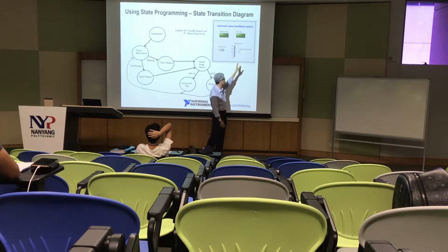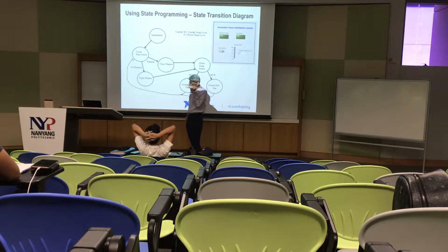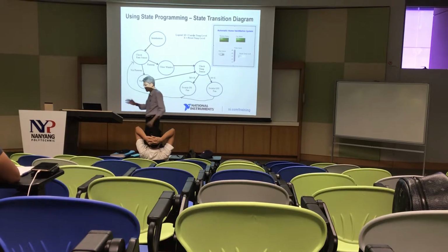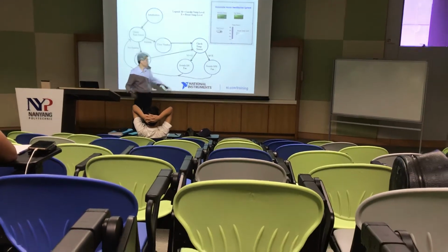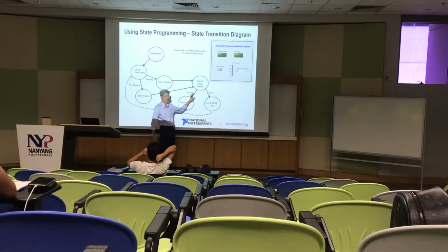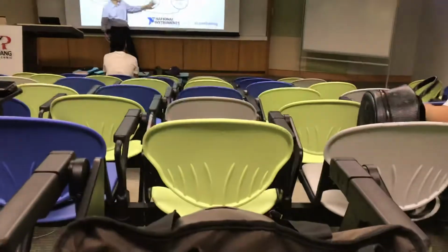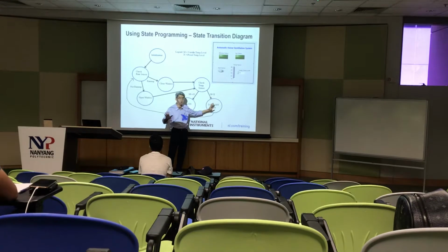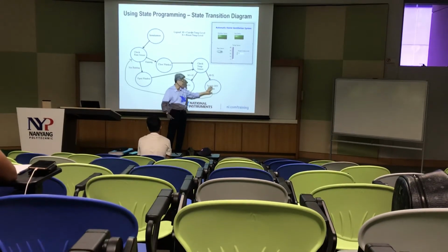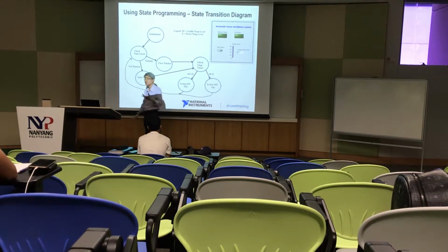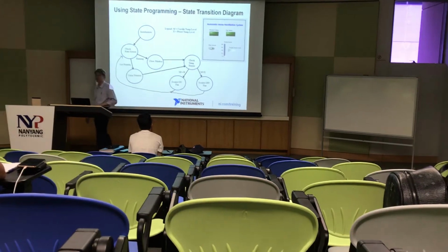Now it's preset to 25. That means 25 is okay. 26, I'm not too happy about it. So if it is greater or equal to 25, I want to switch on the fan to ventilate. If it's less than 25, I'm okay. Not bad. I just leave the fan off to save energy. Not always on the fan, right?